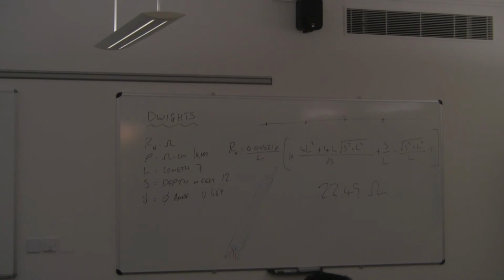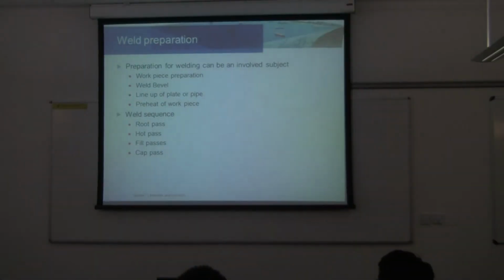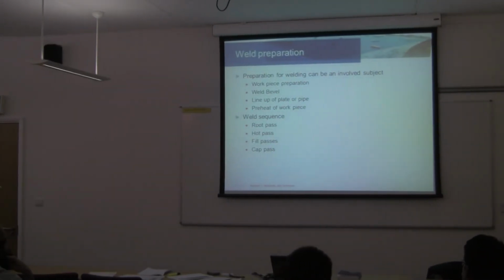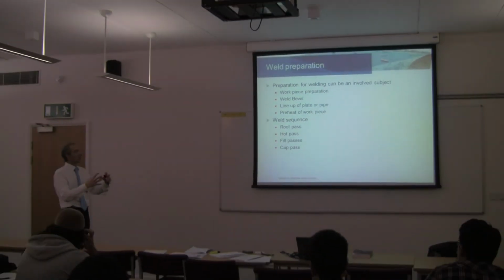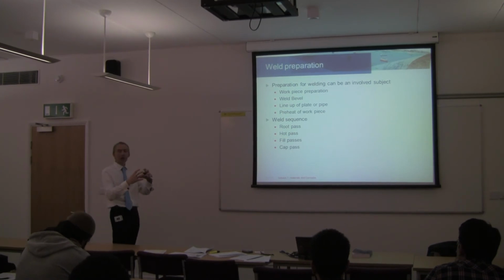The preparation that you require for welding is also equally as important, probably just as important as preparing the surface of the pipeline before you coat it. The weld bevel at the ends needs to be free of grease and contaminants. You need to have it lined up perfectly.